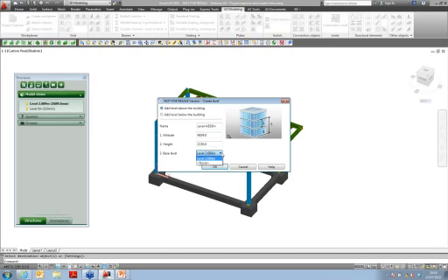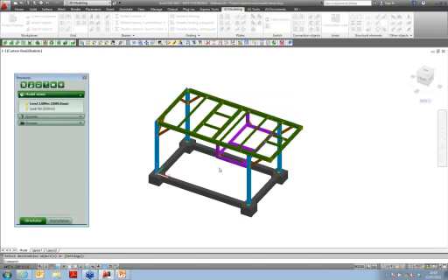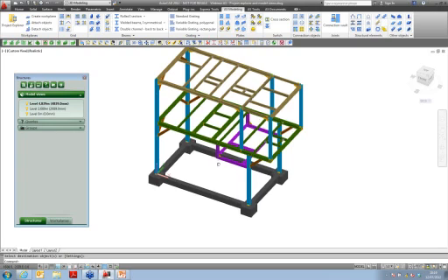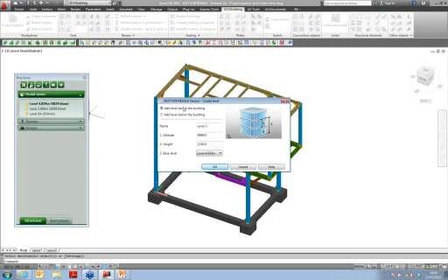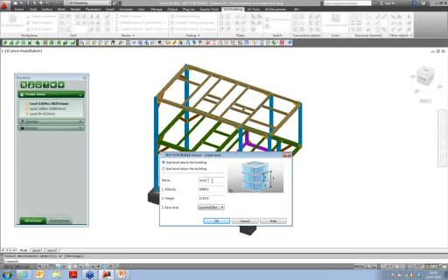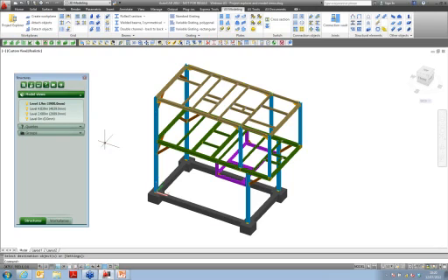So you can specify from which level or what is the difference of height between two levels. Just press OK, and here we go. You get the level which is created automatically. We can create another one. I can, for example, create an intermediate one, something like level 3.9 meter. Okay, just enter the altitude like that. I can specify from which here, something like that. So altitude, sorry. Okay, press OK, and I get my level which appears automatically.